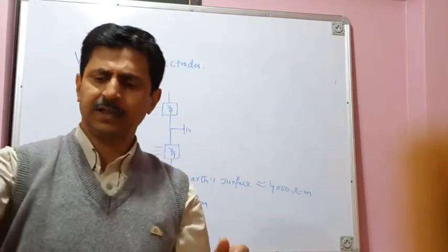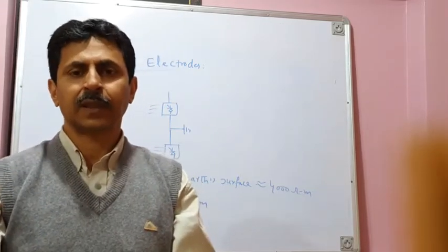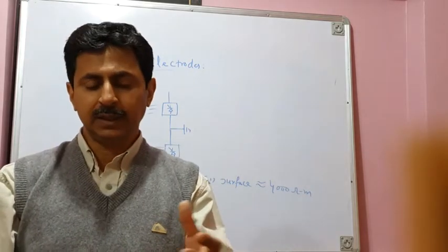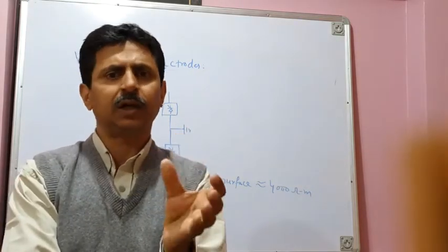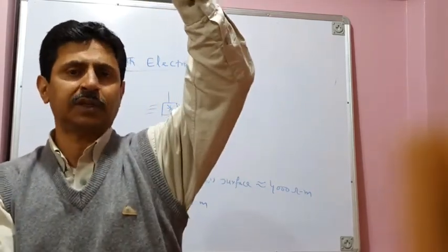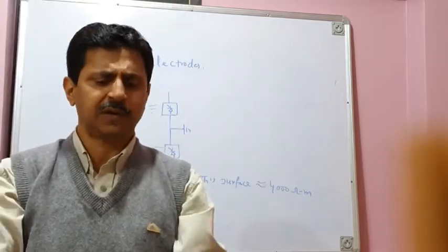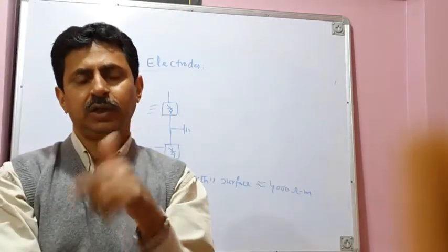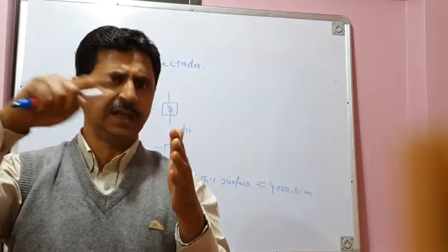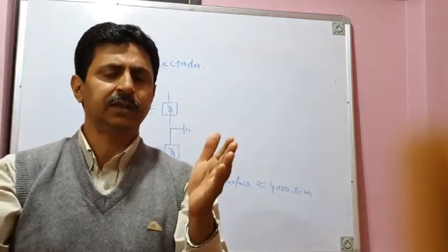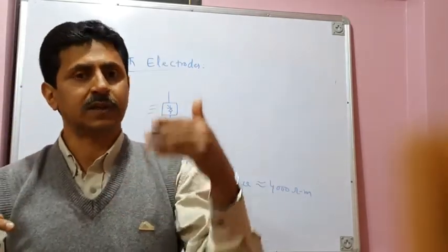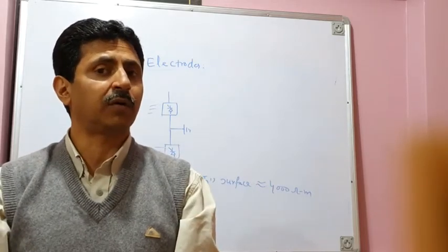The answer is no. If you put an earth electrode near a power line, where a power transmission line is already running, and just below that line you put the earth electrode, then the current flowing through the earth, which is basically Id, the DC line current, has some ripples, and these ripples may cause interference with the power lines.